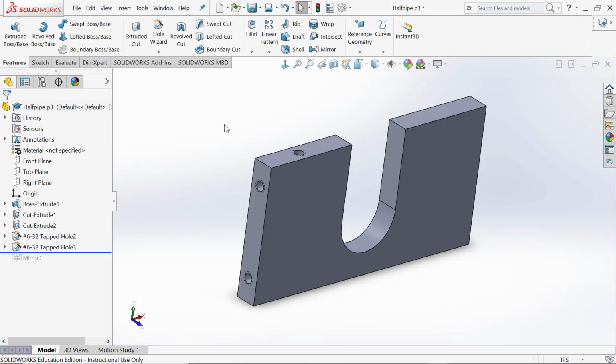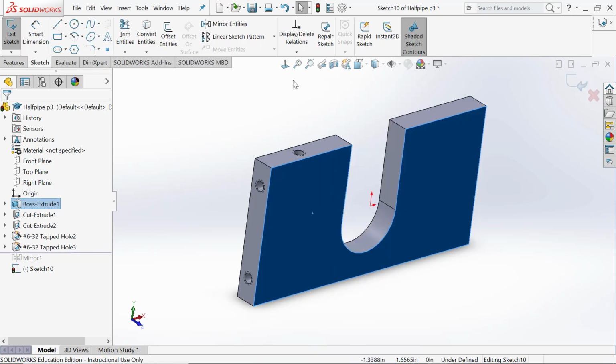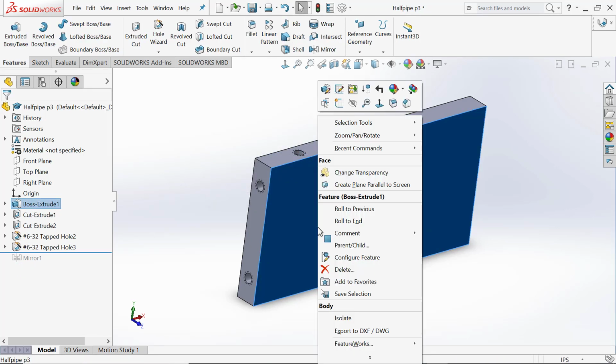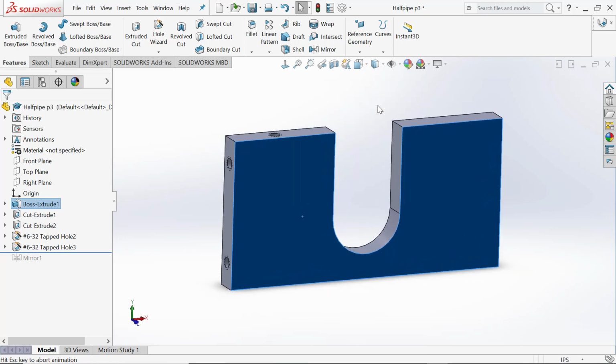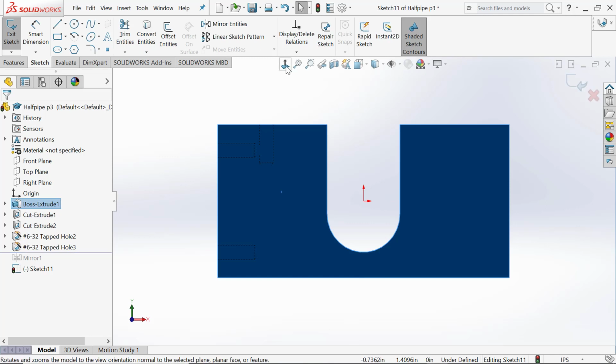So let's just go ahead right now and let's right click on this front face surface that we want to work on and start a sketch. Okay. I'm going to go normal to that. In fact, actually, let me show you something, Sebastian, while you're here. If you right click and first choose the normal to, you just have to think ahead a little bit, and then right click and start the sketch. You don't actually have to have this thing here.